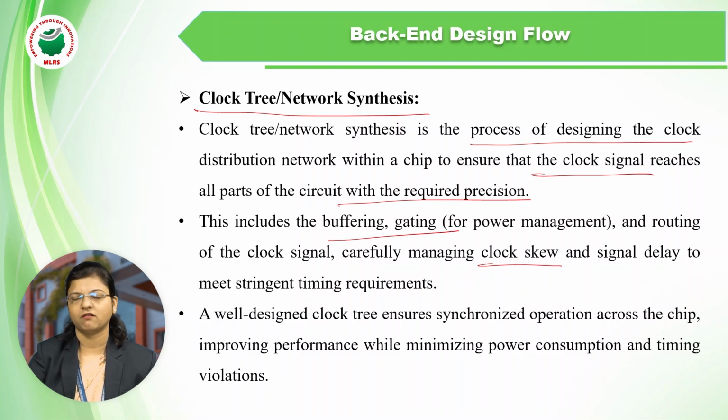Clock gating, as we have discussed, is basically a power reduction technique. We should keep the clock running whenever it is necessary, otherwise we can disable the clock. Clock skew is the difference in the arrival of the clock. If we are not properly managing the clock within that space, we may face clock skew issues and signal delay.